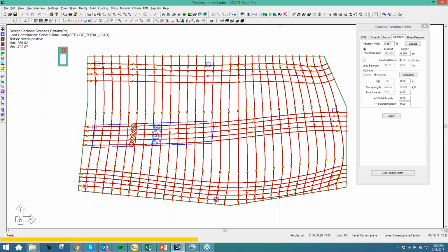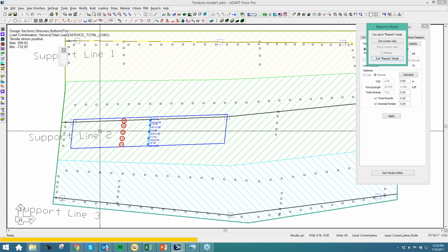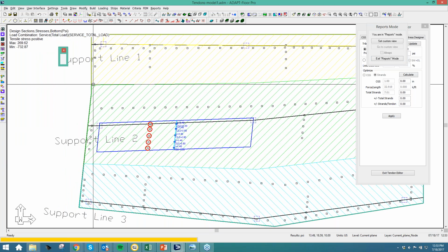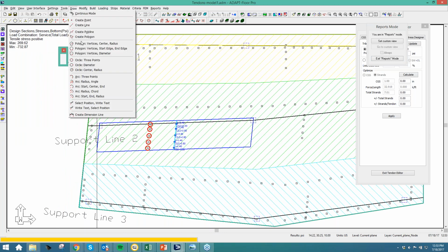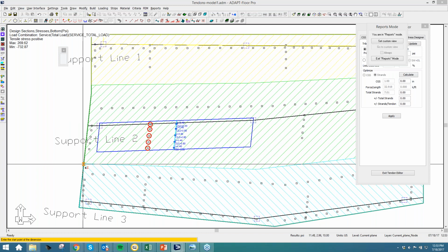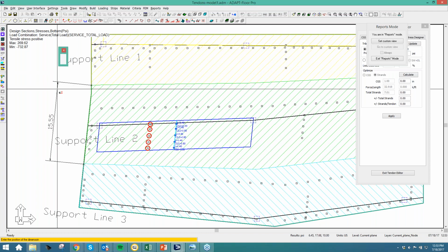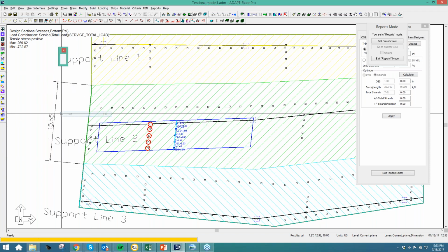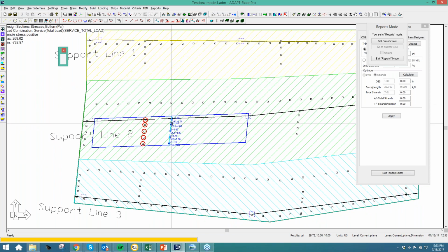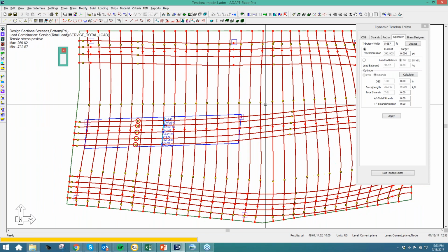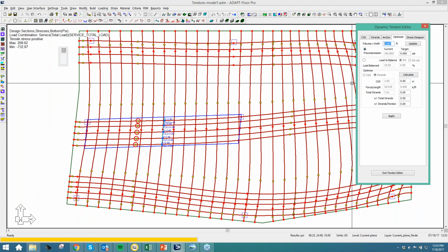If I turn on, for example, the tributaries that have been calculated here, it's going from here to here. And so just quickly getting a sense of what that is, if I'm just dimensioning this really quickly here, this is about 15.5 feet. So I'm going to actually change this tributary region to be 15.5 feet instead of 5 point whatever feet. So if I do that and update, now my P over A, this is completely random, happens to be at 125 right now.